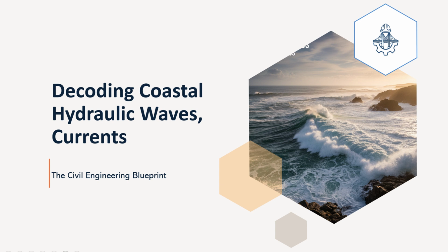The dynamic free surface boundary condition. This states that the pressure on the free surface, the interface between water and air, is uniform along the wave, essentially equal to constant atmospheric pressure. So pressure is constant whether you're at a crest or a trough right at the surface.